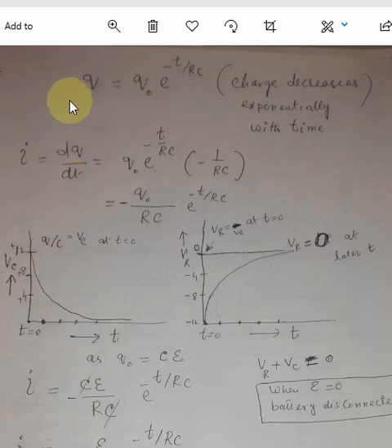Now let us calculate the current. How will we get the current? By differentiating this Q with respect to time, we get current, and obviously we will differentiate the other side too with respect to time. We get Q naught, this exponential term, multiplied by the derivative of the exponent, in which minus 1 over RC is constant and the derivative of t is 1.